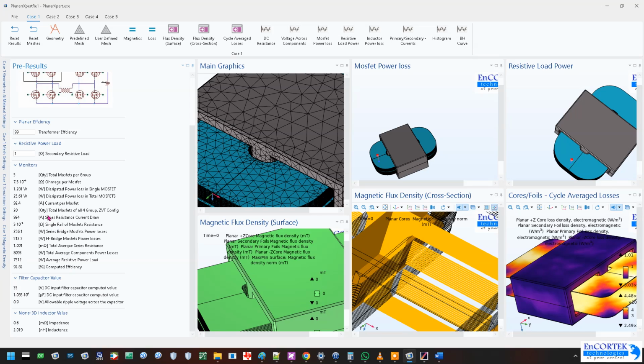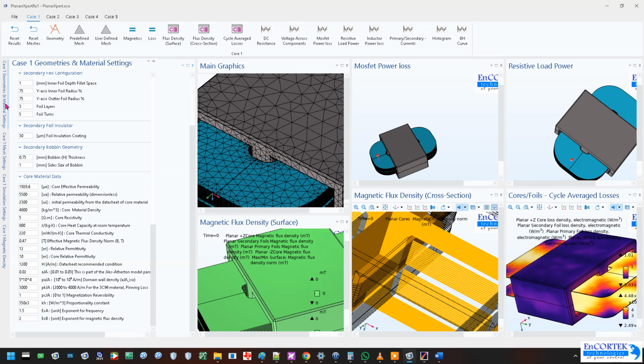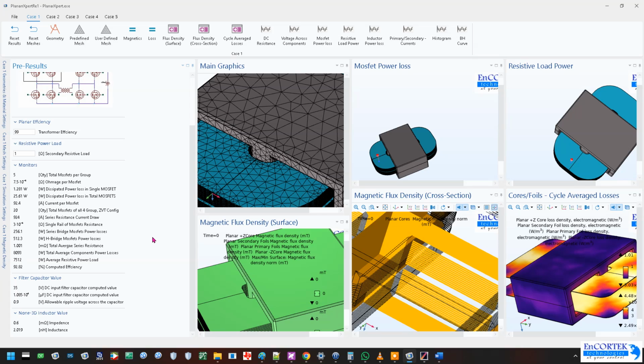And the voltage that went into this was an 18 volt DC battery, and the calculation that we need for the low pass filter is a 35 volt capacitor, right? So minimum 35 volt capacitor, not even 25 volts, 35 volts for 18 volts, right? And the capacitance has to be, this is 10,000 microfarad, more likely 10,000 microfarad, right?